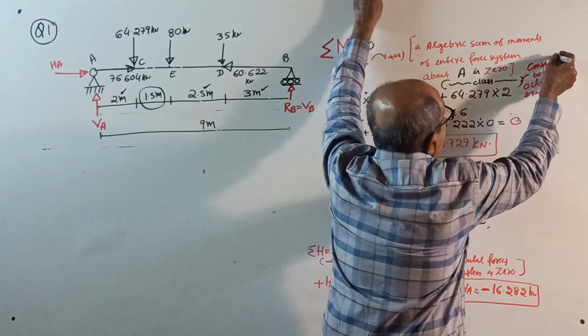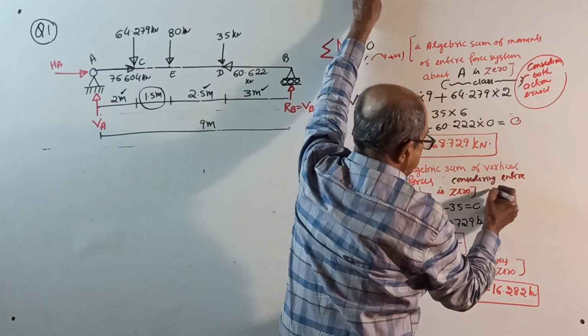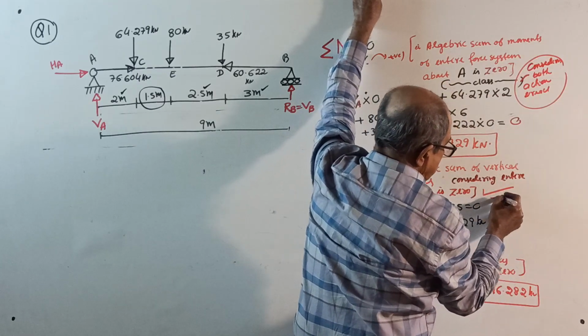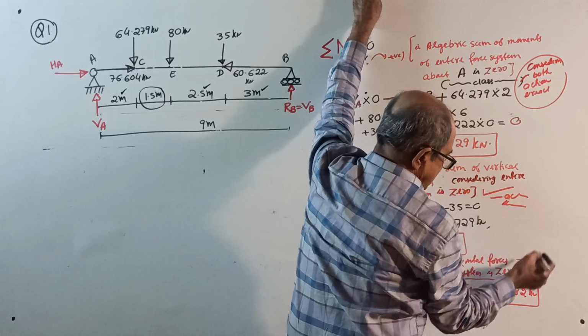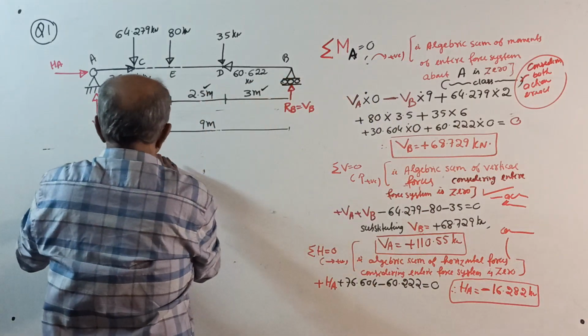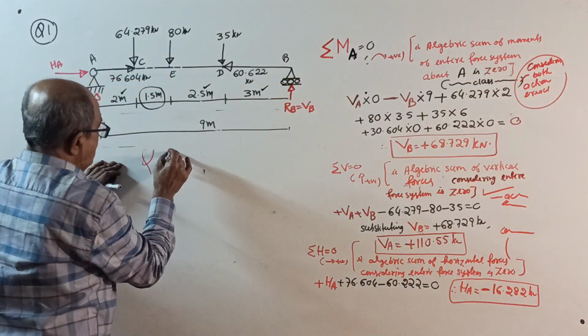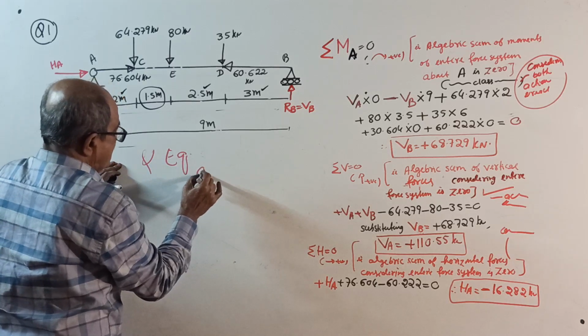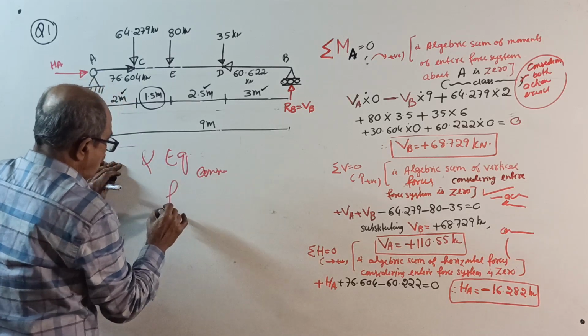Here also, write that statement: considering both action and reaction. And make a note: when you apply equilibrium, consider the full beam.